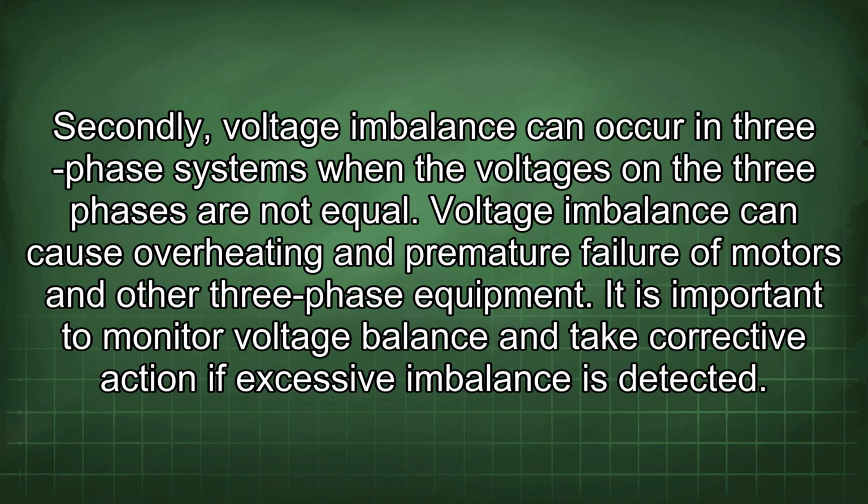Secondly, voltage imbalance can occur in three-phase systems when the voltages on the three phases are not equal. Voltage imbalance can cause overheating and premature failure of motors and other three-phase equipment. It is important to monitor voltage balance and take corrective action if excessive imbalance is detected.